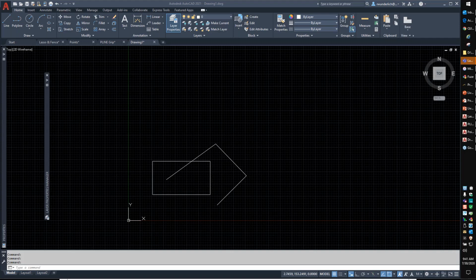Within a block used as visible and hidden in the same drawing, should I set the colors and line types inside this block as by layer or by block, so that I can use the same block twice but show it with the same two colors and line types? Erlinda, okay, this was an excellent question. What I always tell people, unless you have a specific need, is to draw the blocks to always be color by layer, line type by layer.